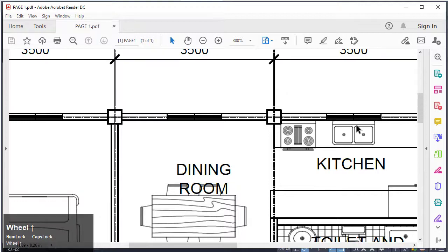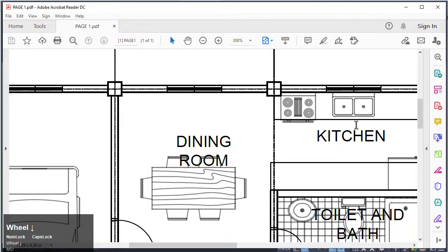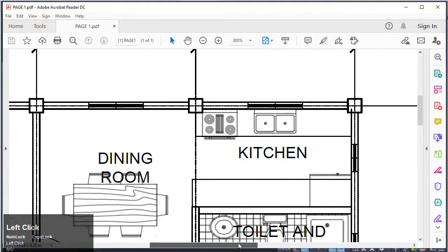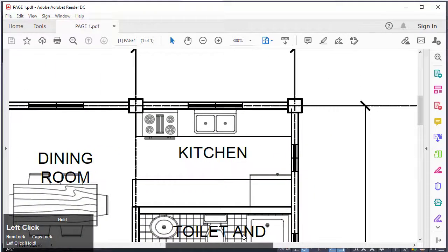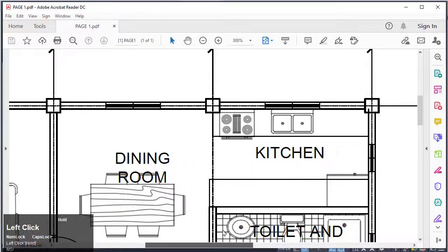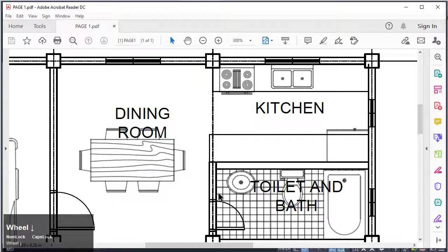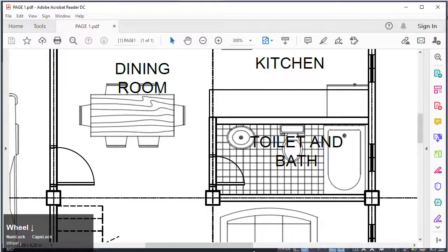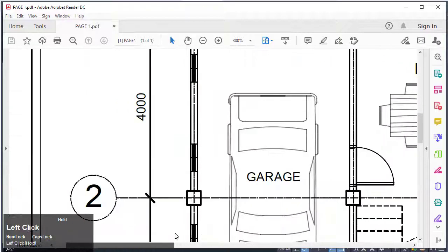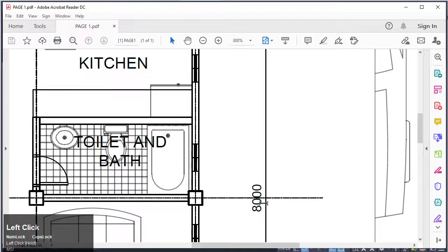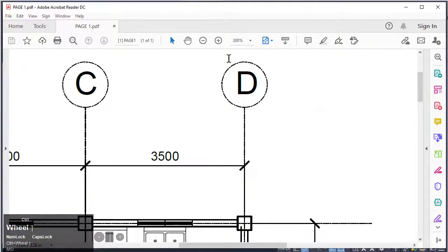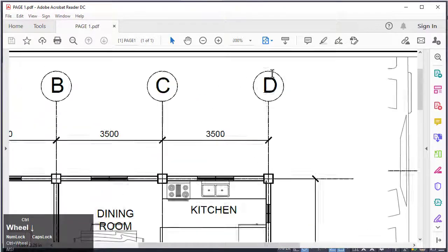As you can see, the layers for our furniture are set to a transparency of 50. That is why the visibility or the darkness of the line is semi-transparent as reflected in your PDF. The lines, although colored in your AutoCAD, appear to be black in your PDF file. You can adjust your layers so that the corresponding spaces of your dashes will adjust.